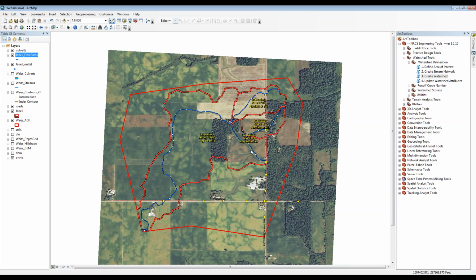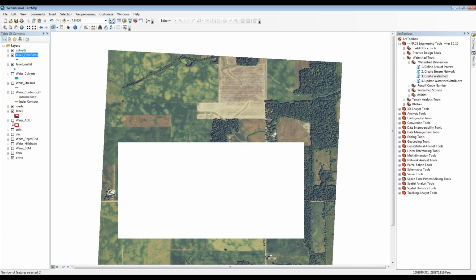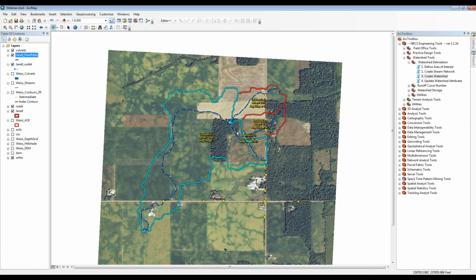One of the things we'll see here, it's hard to see if this basin area includes the subbasins that are nested. A good way to check what's all included is to use your Select Features tool. So if I turn off my AOI and select my large basin, I can see that the nested watersheds actually aren't included in this overall acreage